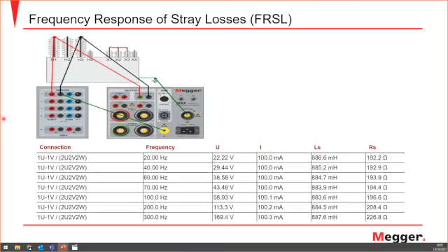And this is the connection, just like the previous short circuit test, where we have the short on the low side, and we are connecting between phase 1 and phase 3. This is only for the first phase, but for all other phases we would need to repeat the connection. I will show in the next minutes how to run this live on a real power transformer and measure it together, and then I will take your questions as well.